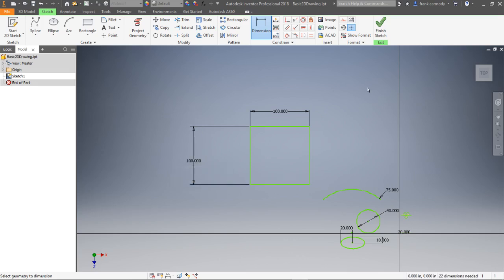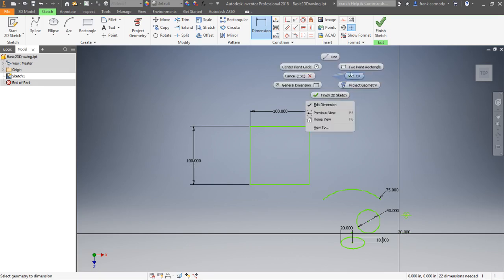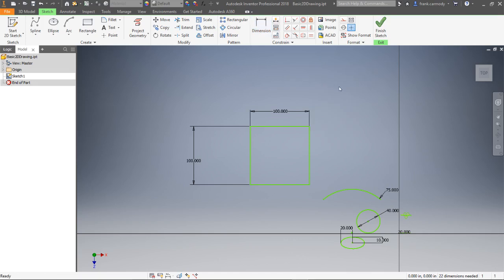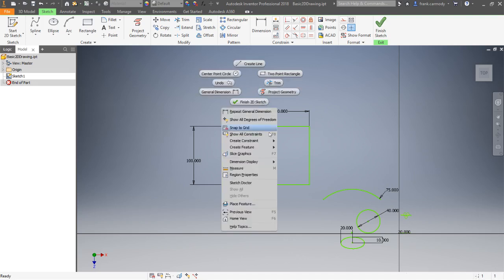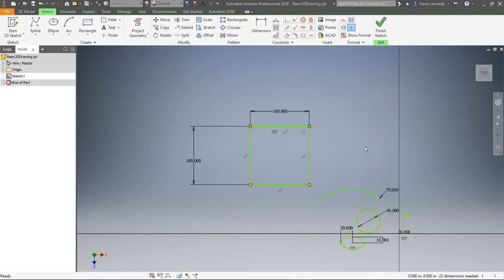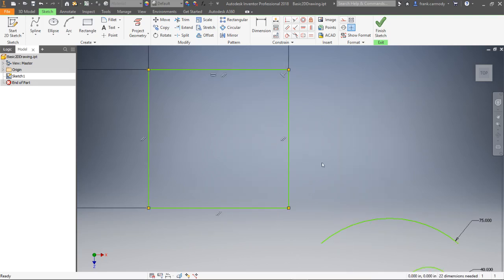Okay, right now what I want to call your attention to, so I'm going to right click, and then I can right click and then just right click again if I want on that heads up display as well. What I want to call your attention to right now is not something I want you to focus on this time, but I want to call your attention to the constraints. Okay, so I right clicked an empty area and I'm clicking show all constraints. What we can look at on this square is that a square is a collection of lines that's defined as a rectangle by 2-dimensional constraints.